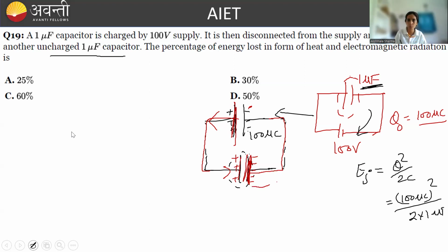So it will flow from here to here. So it will lose its positive charge. So it will start acquiring negative charge because initially it was neutral and its negativity will drop. All this will happen until their potential difference becomes the same. So finally, their potentials are becoming the same. It means these two capacitors are in parallel, and they will have a common potential of V.